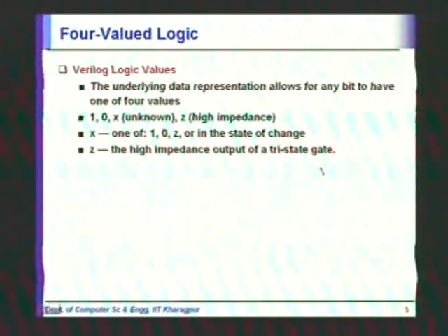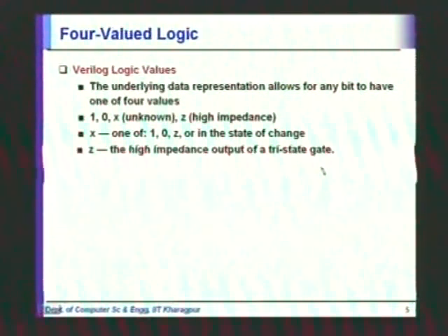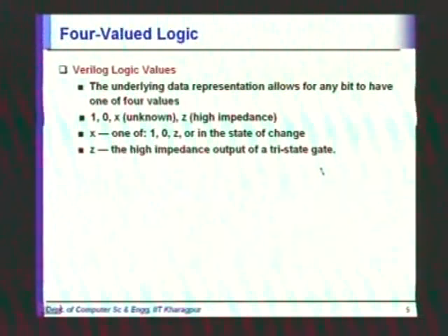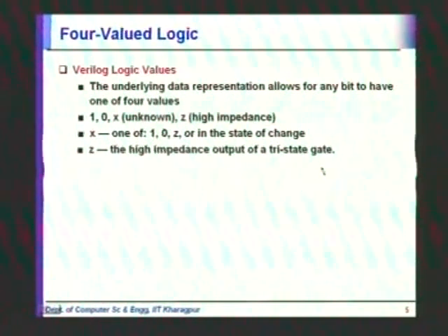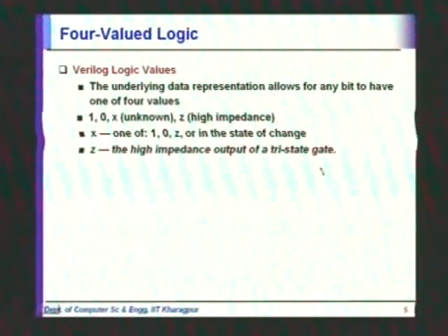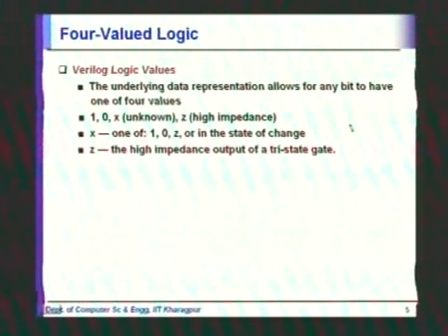Different devices should not drive the bus at the same time, because then we will have collision in the signals, right? So what are the other outputs that feed into the bus going to be in? They are going to be tri-stated, right? So all except the current driver will be tri-stated, right? So that's why tri-state is a very important component, and we cannot simply ignore tri-state.